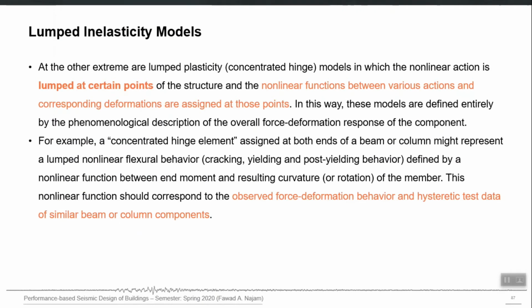Lumped inelasticity model, the other extreme, or concentrated plasticity model or plastic hinge approach, assumes that the nonlinear action is lumped at certain locations in the structure. The whole structure is not nonlinear. Each point in the structure is not nonlinear. Only a few points can exhibit nonlinear behavior, and the overall nonlinear effect is lumped at those points, right? So we directly define the nonlinear action versus deformation behavior at those points only, right?